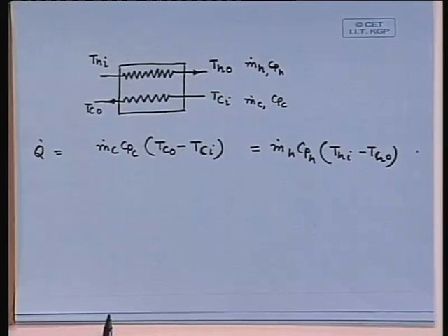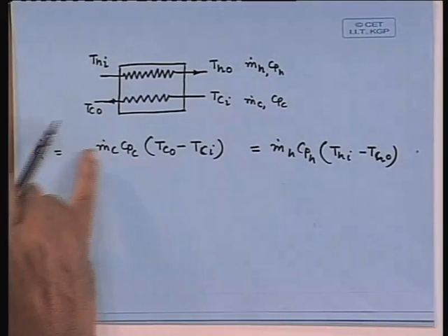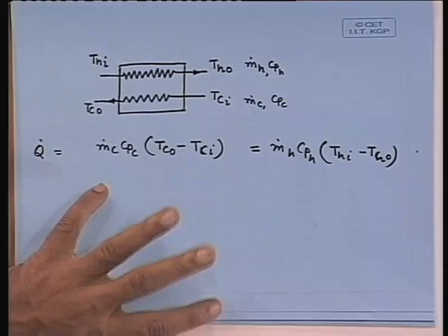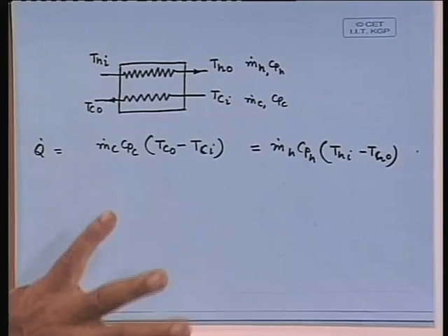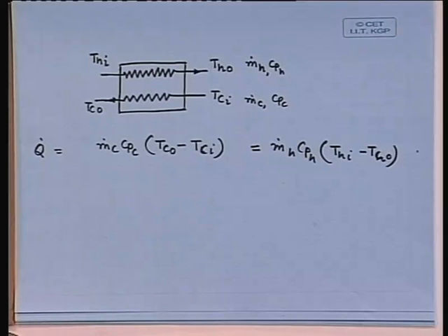We will have the highest temperature differential for the medium which has the lowest product of specific heat and mass flow rate. So, this is actually the heat capacity rate. This m dot Cp is the heat capacity rate. So, the fluid which has the lowest heat capacity rate will have the highest temperature increase. All right.